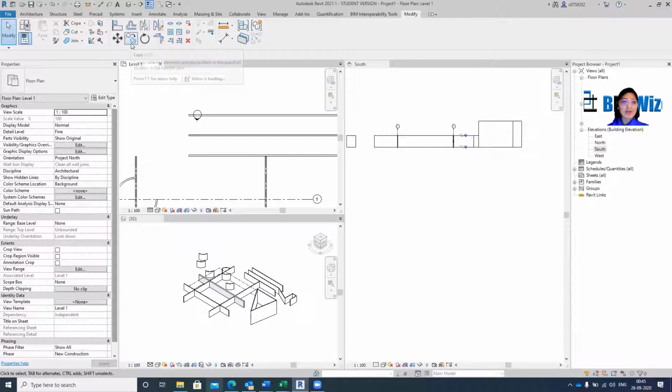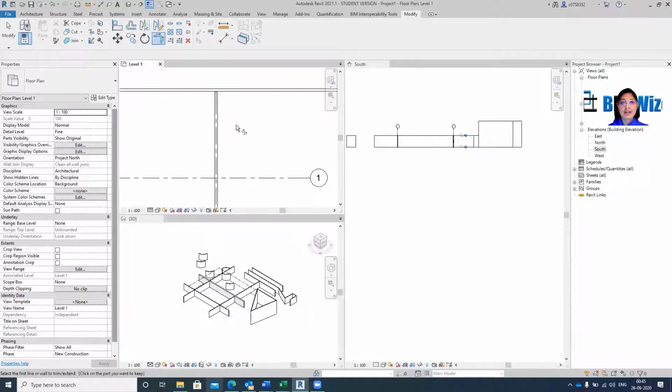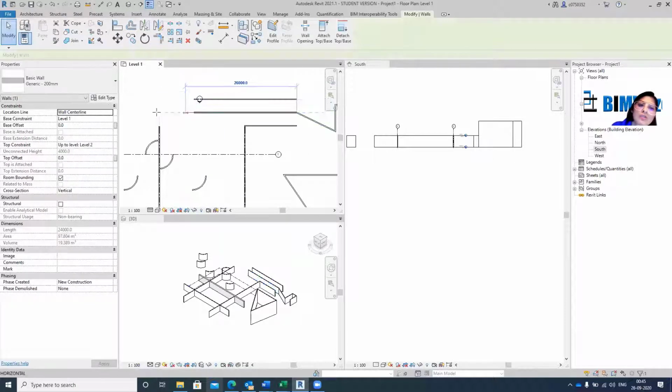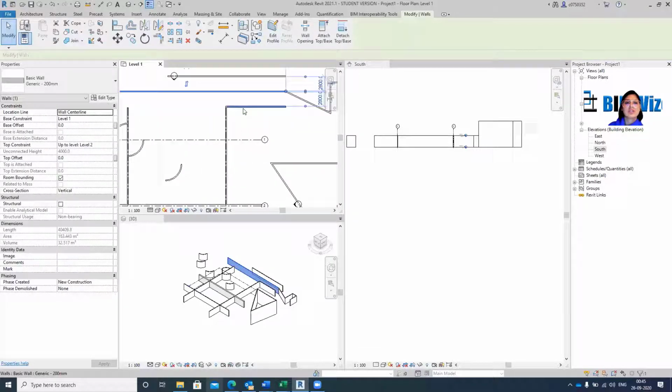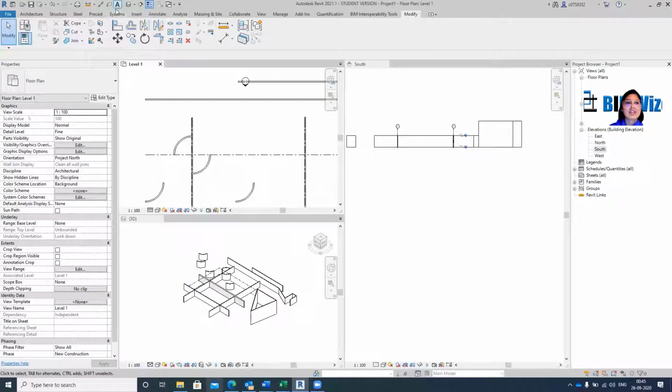The next thing that we would want to do is fillet. Fillet is my all-time favorite. You can do fillet from here. Now if I want all of these walls to touch this, let's delete this. If I want all these walls to touch here, I just go extend single element or multiple elements. So I select this, the side that I want, select, and I can go here.